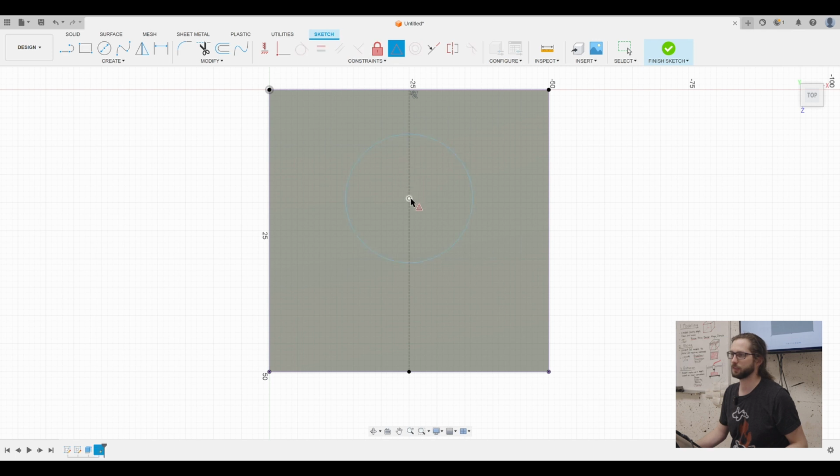So we'll click the circle. So that's the first thing. And now we need to tell Fusion which thing we want it to be on the midpoint of. I want it to be on the midpoint of this line, right? So now we have that midpoint constraint. Just like what comes up when it shows you the triangle, again, that's just Fusion pre-applying one of the constraints that we have access to, just because it's something that you, as a designer, do all of the time. Gotcha. It's trying to make it easy for you without having anything else. Yeah. Okay.